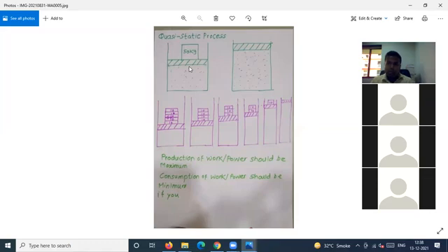And whenever such a process occurs, the path which the system follows while moving from the initial state to the final state is a combination of non-equilibrium states. So the piston will move from the initial state to the final state by following non-equilibrium processes, because you remove the weight suddenly, the piston moves very fast, and it will strike. Now try to understand what is quasi-static.